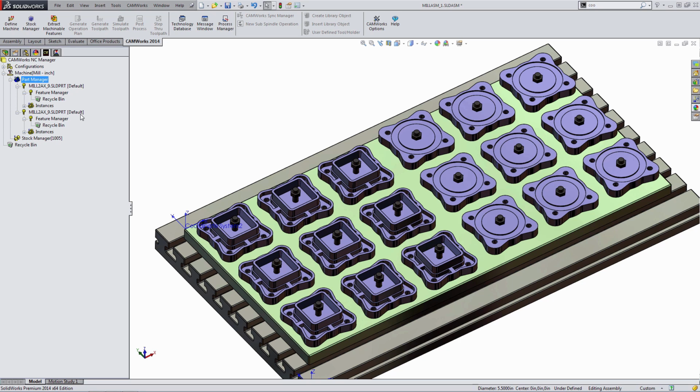Imagine a scenario where we're stepping through stages of a part, where we have a fixture, and on the left-hand side of the fixture we have a fresh part. In the middle of the fixture, we have a part that has gone through the first step, and in the right-hand side, a part that's gone through the first two steps already. After each program runs, we just move the part down the line, kind of like an assembly line. That's a very common way of machining, and this would be a perfect example of how to do that.